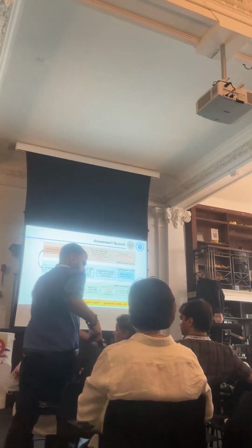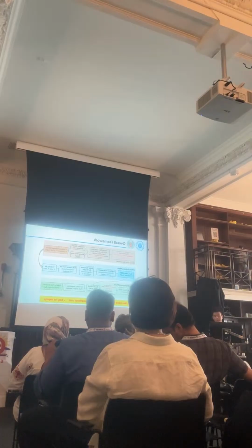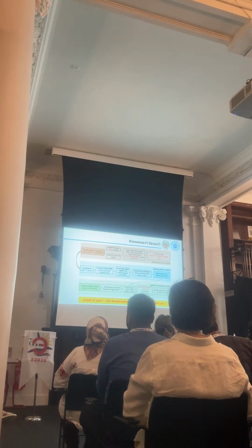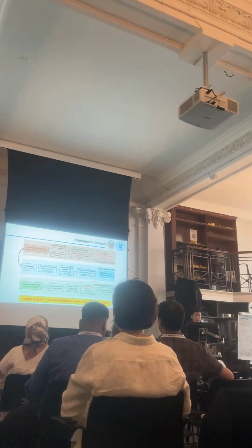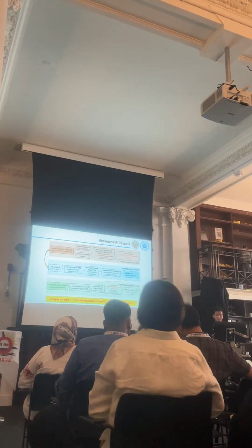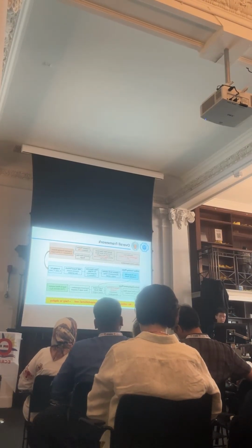In the online phase, we use a circular buffer to store the last 30 seconds of real-time sensor data. We compute the same 14 features, then feed them into the trained RBF model to get the pitch angle command, then send it to the pitch actuator to generate the final pitch angle. So the advantages of our framework are that there's no online training, it has a fixed computational cost for each step, and it's easy to deploy.